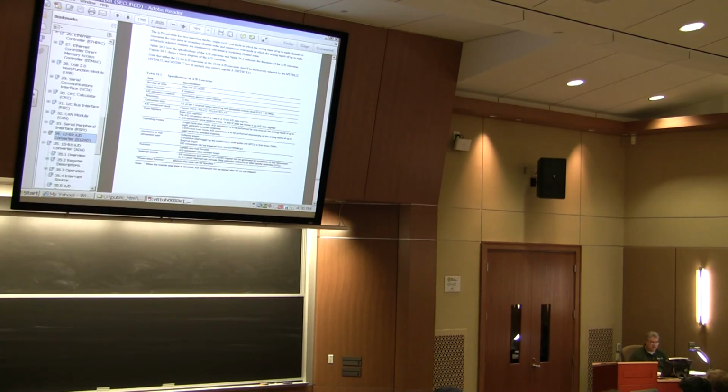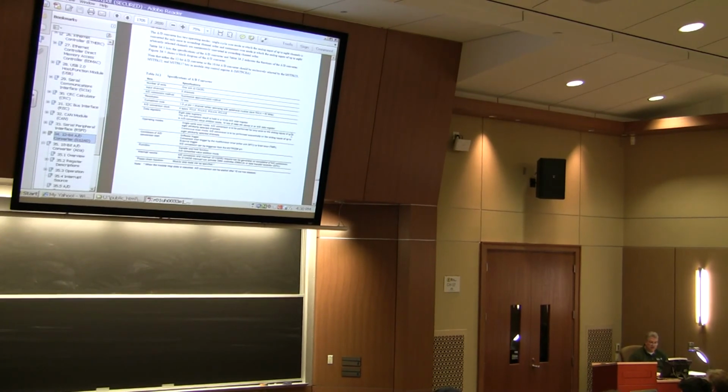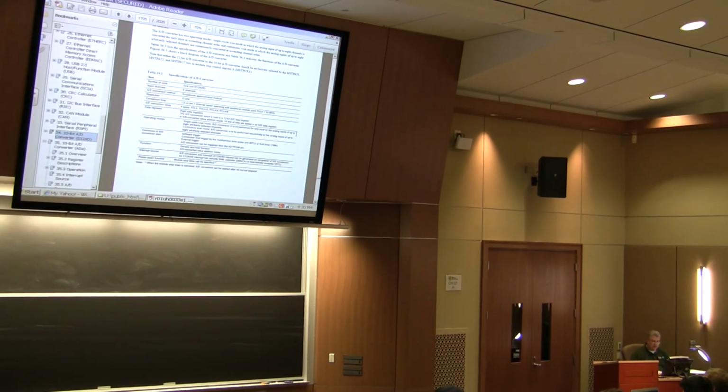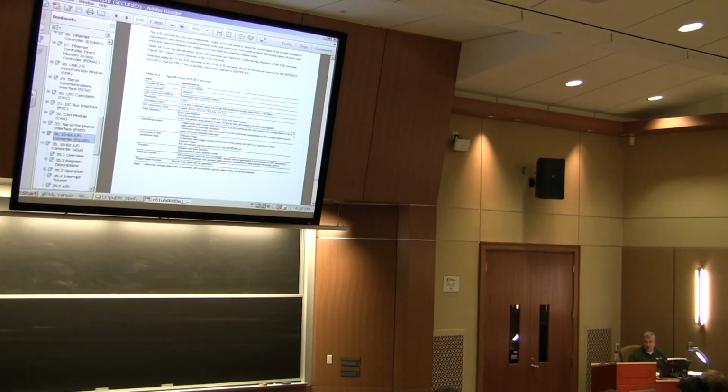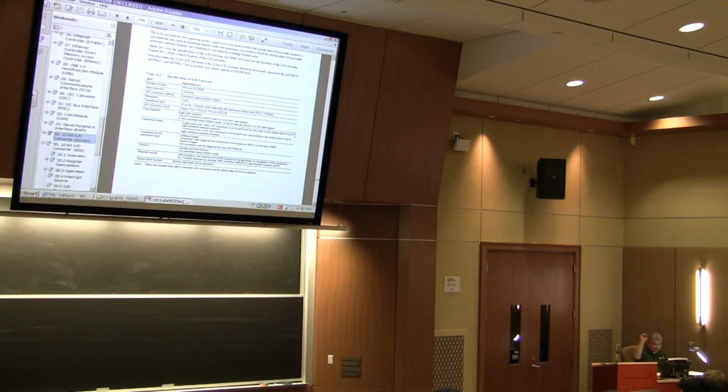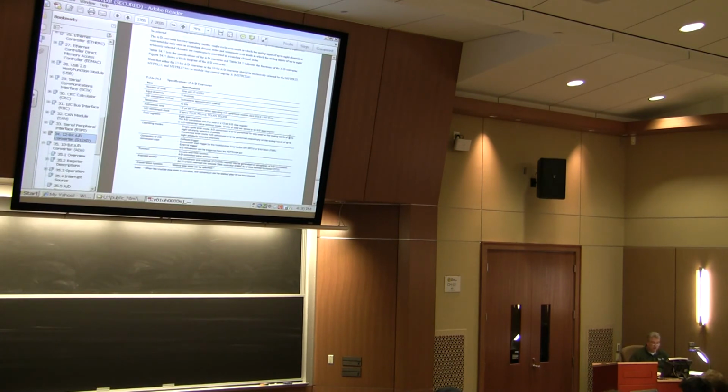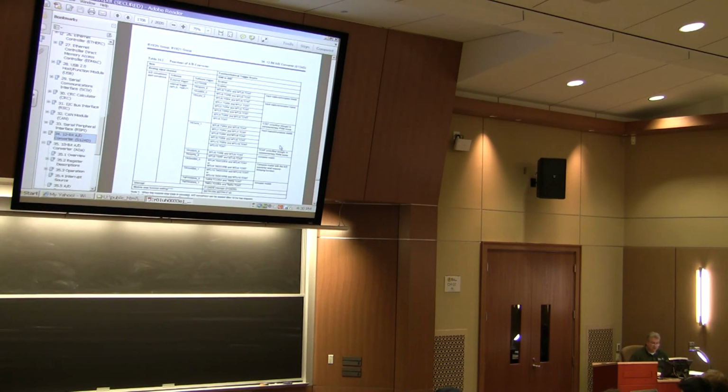And again, single cycle scan. A to D conversion is performed only once on the analog input of up to 8 arbitrarily selected channels. So it looks like you can just say, measure all 8 once, and then you'll be able to go and read that.